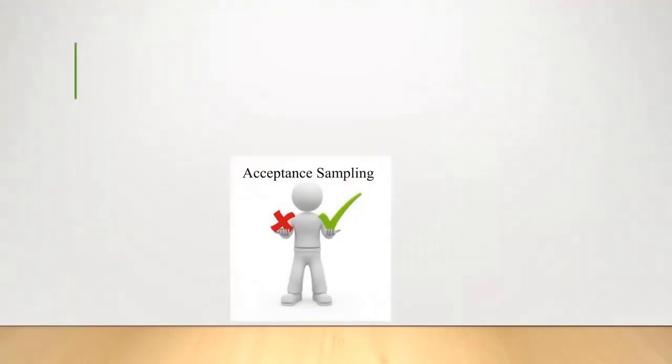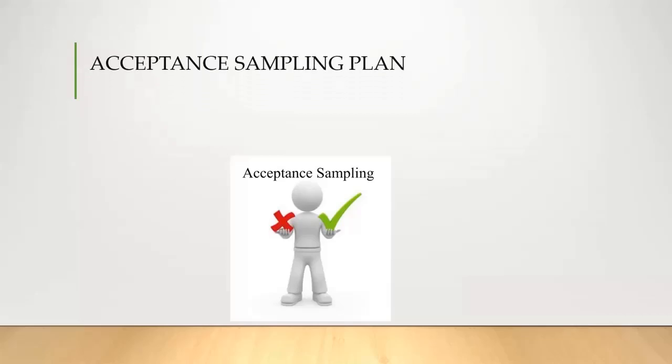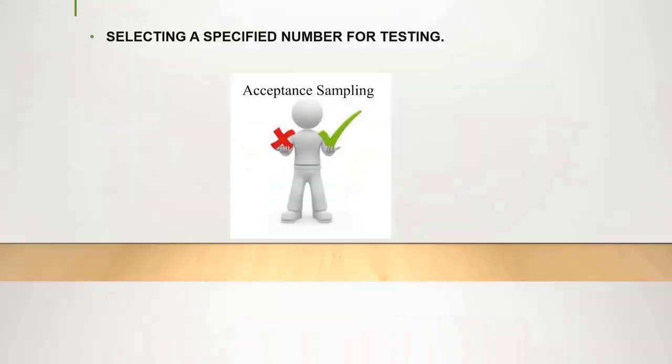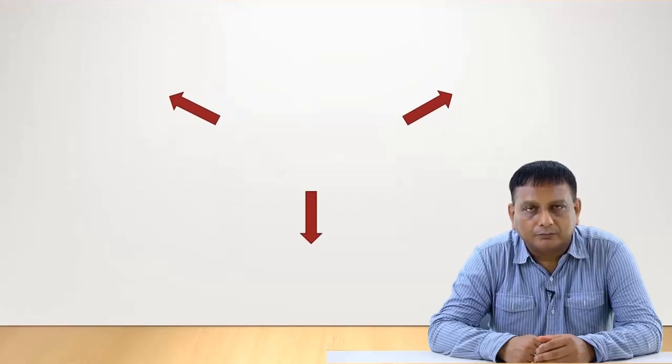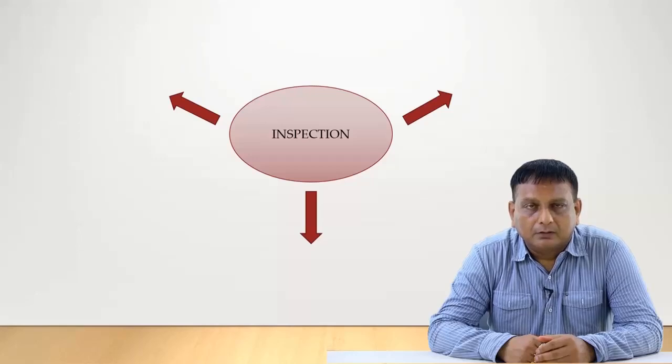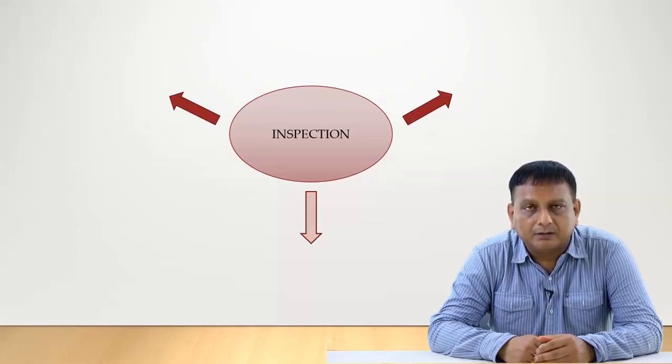Next comes acceptance sampling. Here a lot of buyer nominated sampling plans are there, what the buyer accepts. So the AQL system comes into play. Under this AQL, how many major defects and how many minor defects are accepted, that comes under the acceptance sampling plan. The buyer normally specifies which type of sampling plan should be followed, and the factory should follow it.